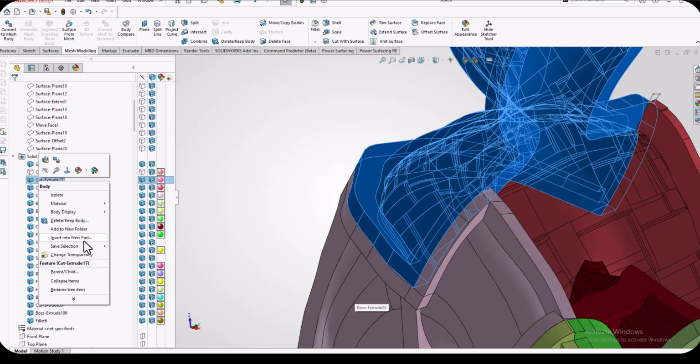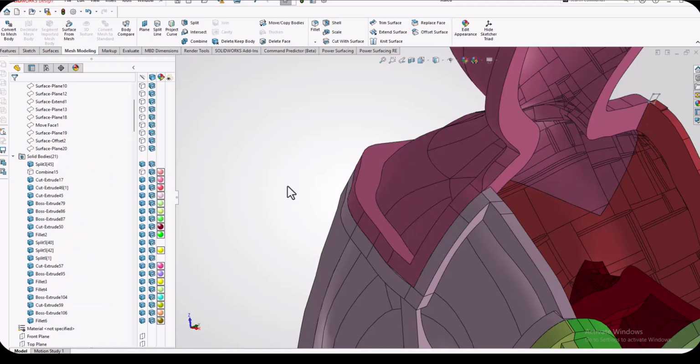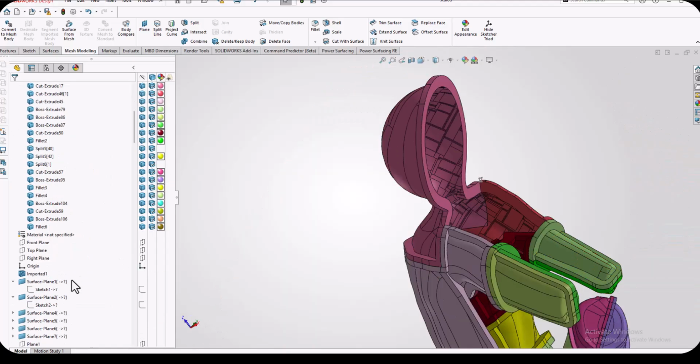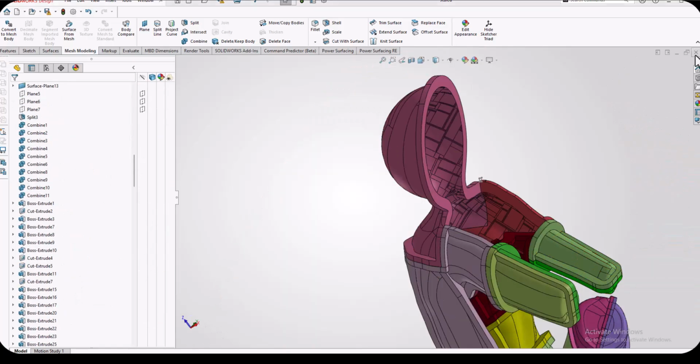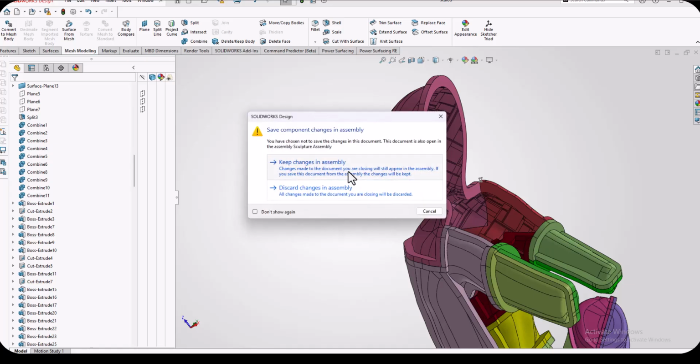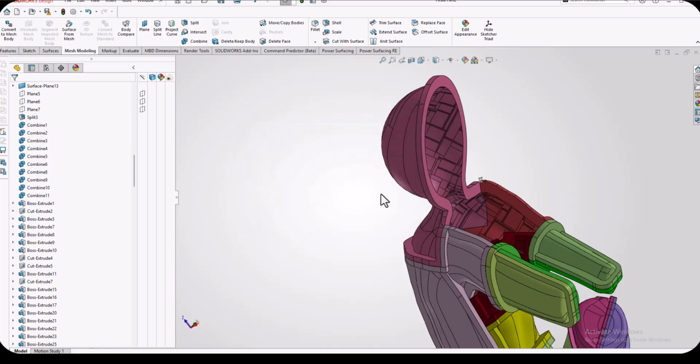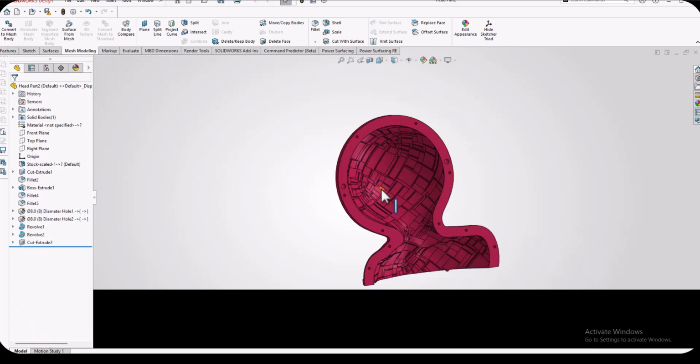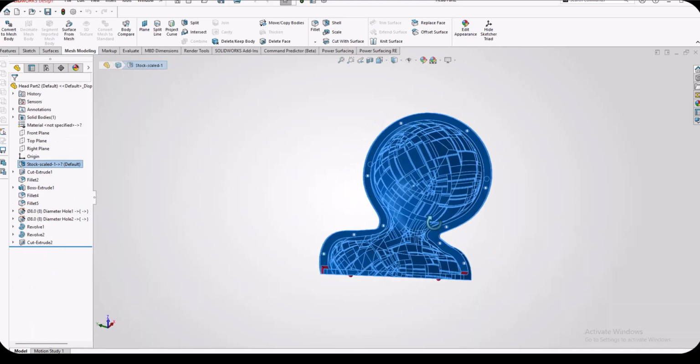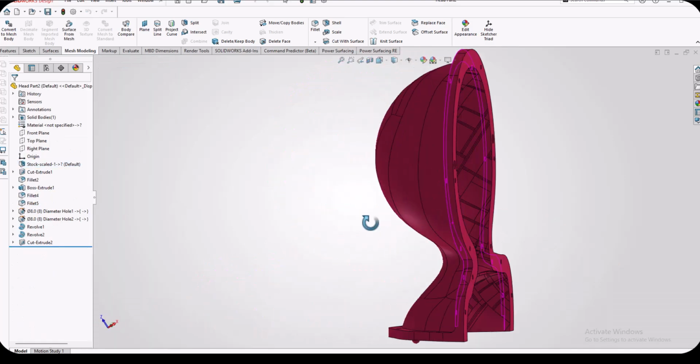If you prefer, you can also create all the alignment holes and fastener features at this stage. Personally, I chose a different workflow. After saving each mold section as an individual part, I added the locating pins, alignment holes, and fastening features separately inside each part file.